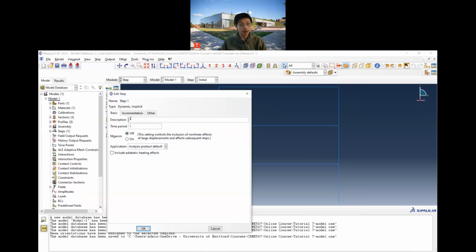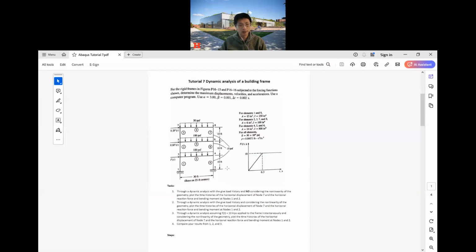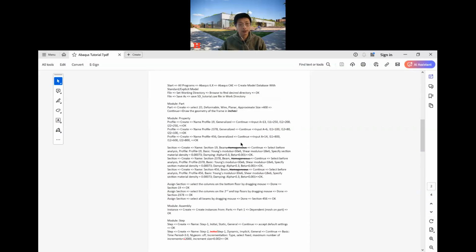So here we need to input how many, set the time step, and so firstly we will try to use time step 1, that's a static load. We apply all the static load. Secondly, we create a dynamic load here.